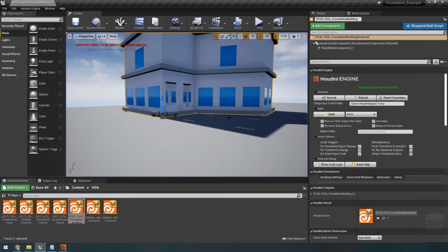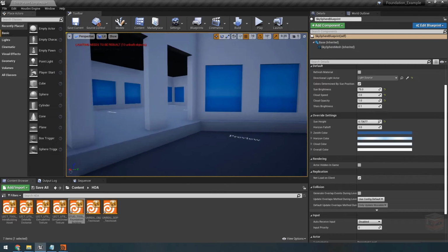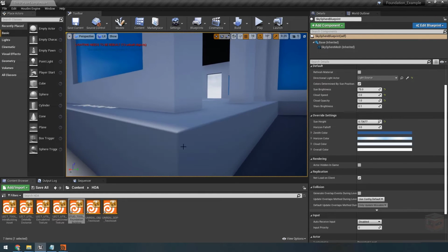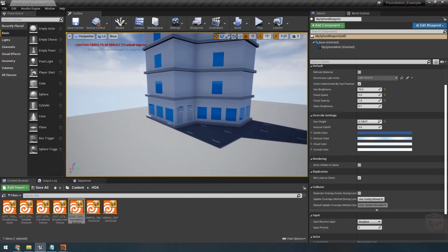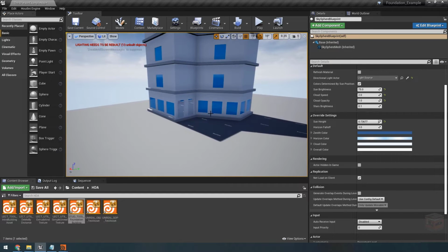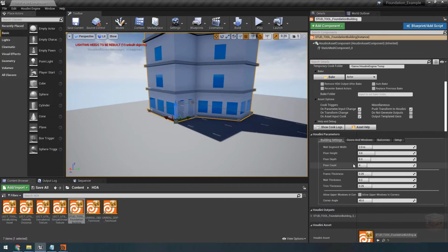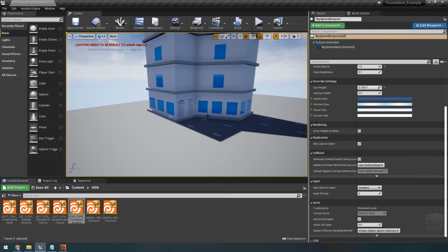When you bevel an edge, it adds extra geometry to that edge, and it turns out Unreal has a couple of issues navigating this particular ledge here, at least based on the collision for the player. The player does have a step height, and that step height should be able to get up the 0.3 or 30 centimeter high ledge here, but with that bevel the player just can't do it.